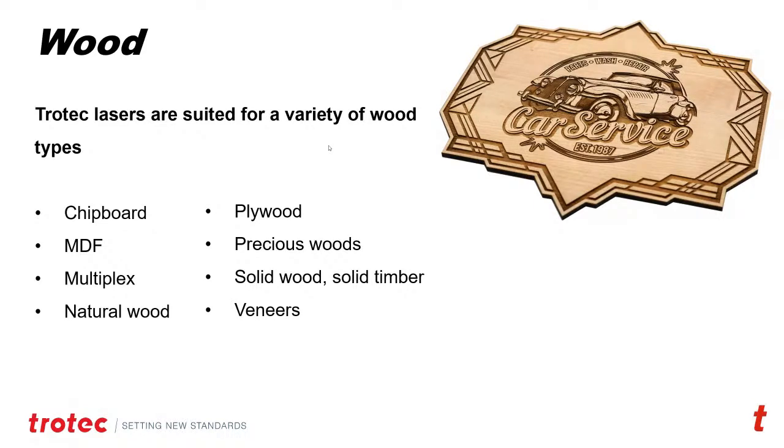All woods are going to work. What I do suggest is if you are using wood with the laser system, make sure that wood is completely finished before you process it with the laser. The reason is the wood has to be sanded down and smooth, and then it's been finished with a polyurethane, a lacquer, or a varnish prior to being processed with the laser.